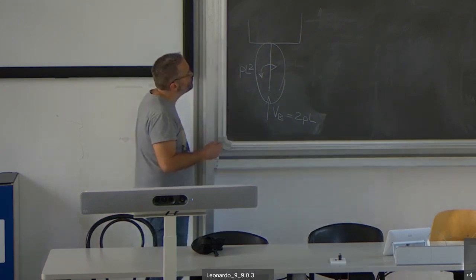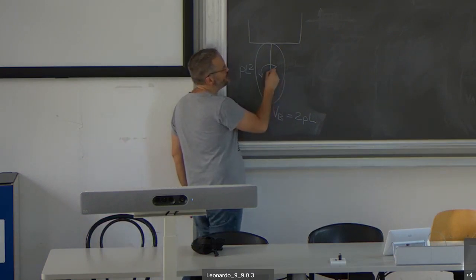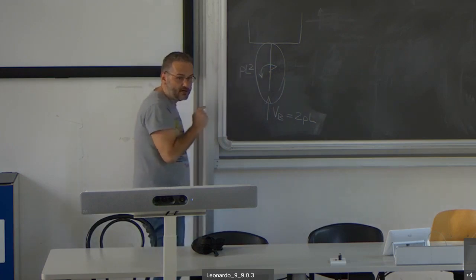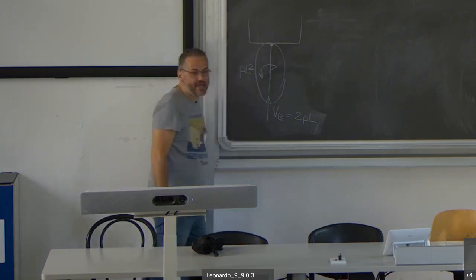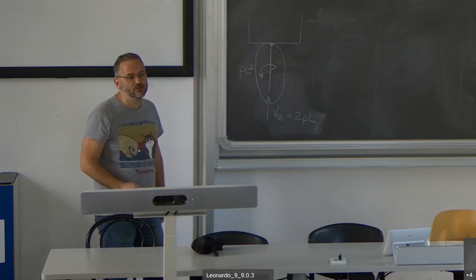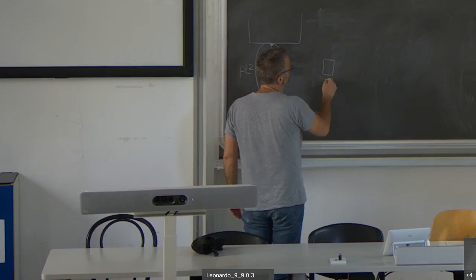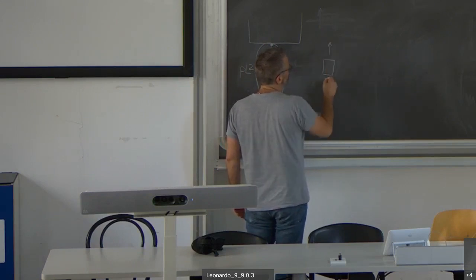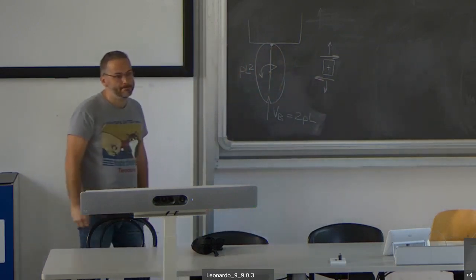So what I'm going to do, I'm going to study the beam up to the point where the concentrated moment is applied. So imagine I'm getting the internal forces values at a point just before the concentrated moment and then at the top. Okay? These are the 2 points I'm going to consider for working out the internal forces. It's a vertical member, so again, tension for axial force and clockwise for shear. Okay?